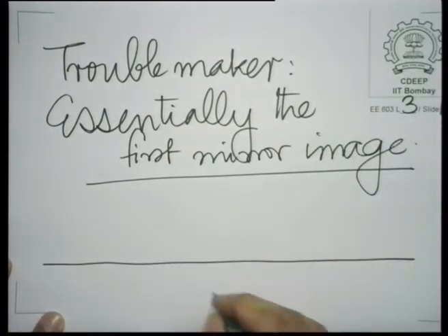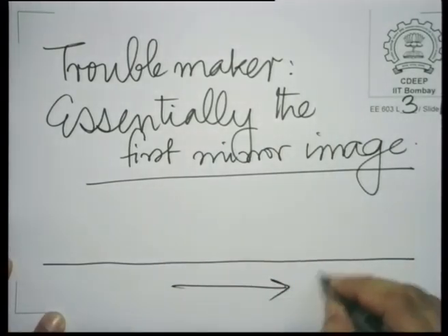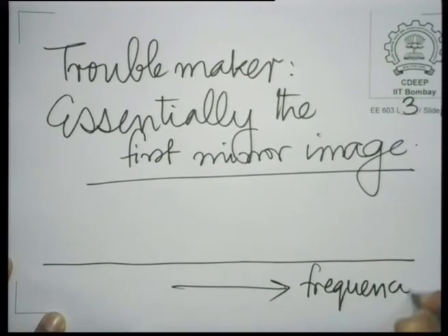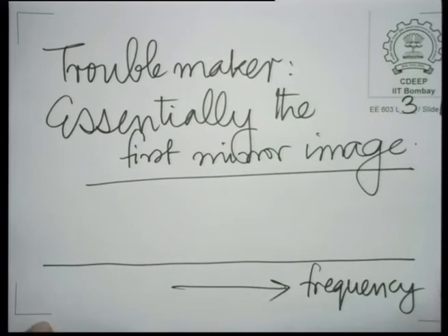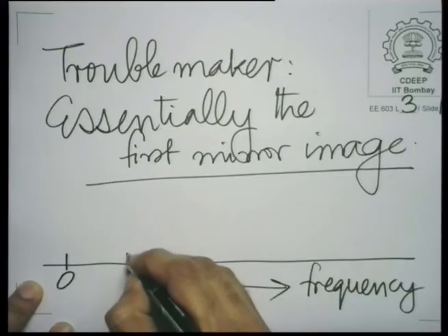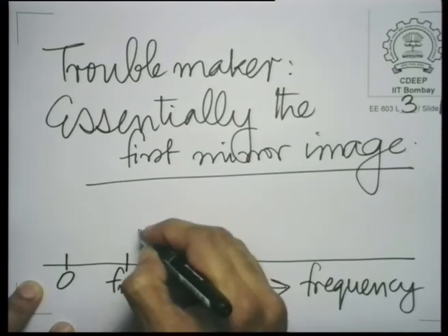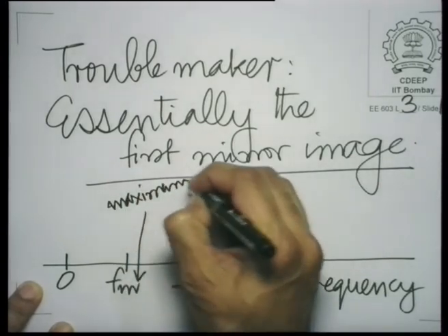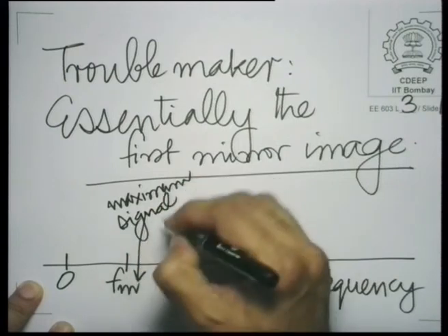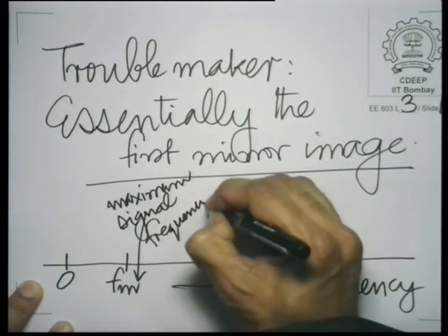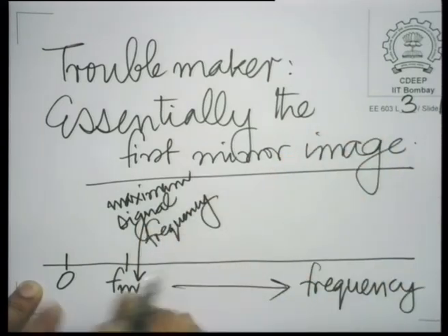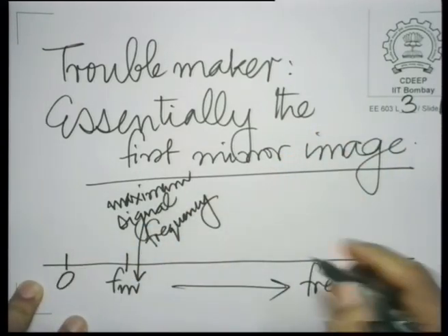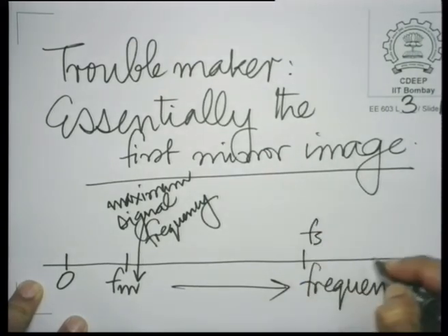So, you see, again let us write this down on the frequency axis, and this time let us use more general symbols. Let us not confine ourselves to this 1 kilohertz, 0.1, 0.11 and so on, right. Let us use 0 to Fm, this is the maximum frequency or the band occupancy. So, we will say that whatever sine waves there are in the signal are all between 0 and Fm, and the sampling frequency is Fs.